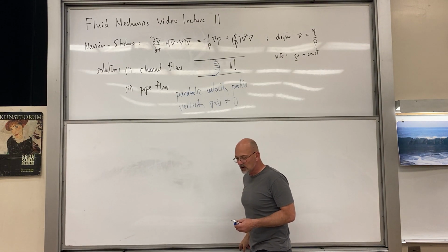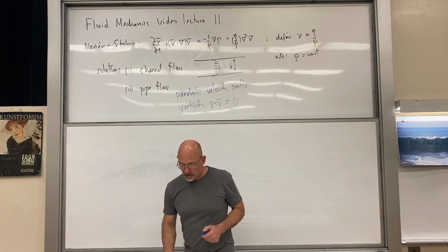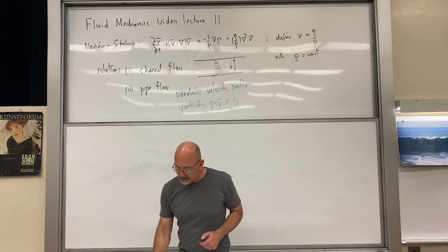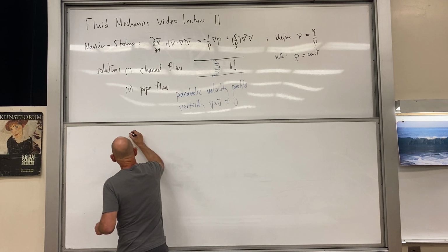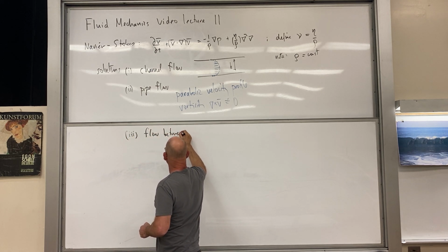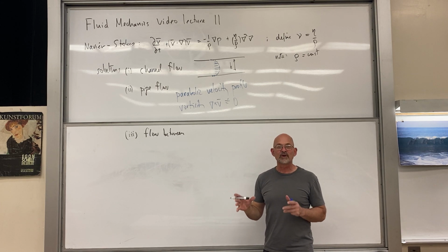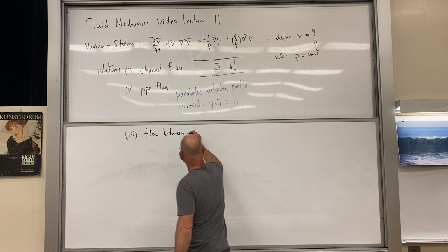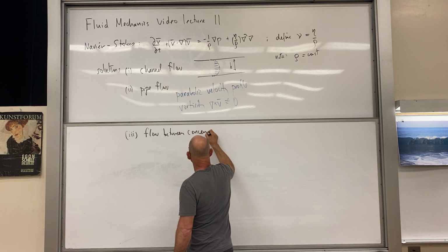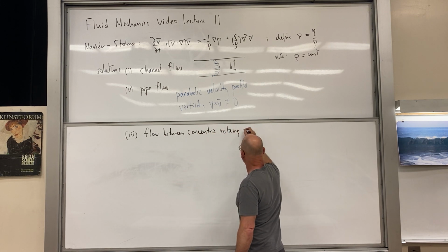Now another flow that one can get an exact solution for is flow between concentric cylinders. And not only between concentric cylinders, between concentric rotating cylinders.